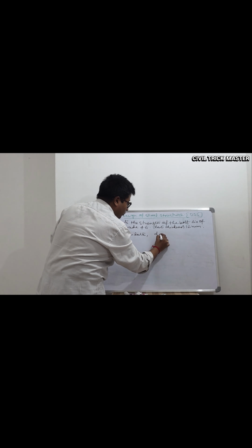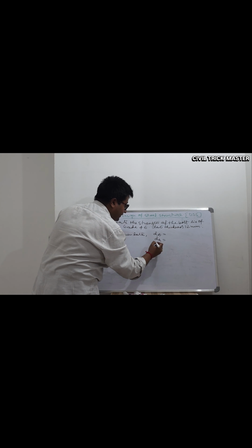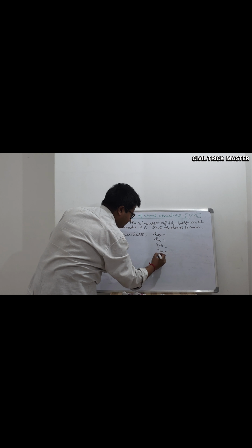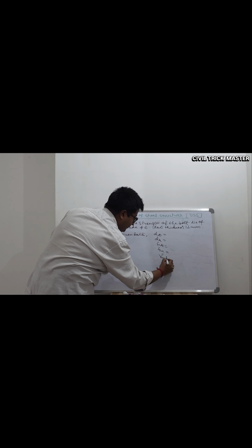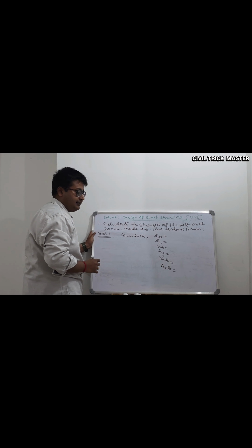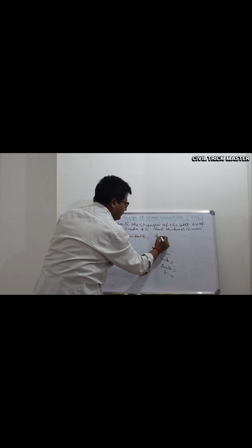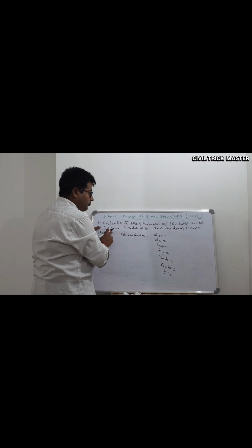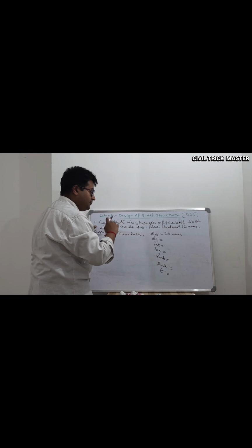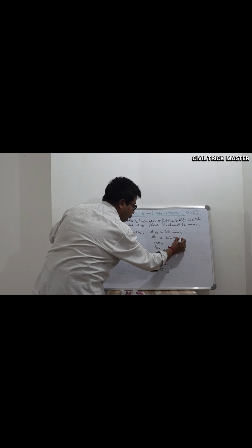The d0 is given. We can calculate from here dh, fub, fu, gamma mb, Anb, that much, and here also t as well. So what is that d0? That is our bolt diameter, that is 20 mm, right? What is that dh? As per our previous formula, we should add plus 2, that means 22 mm.